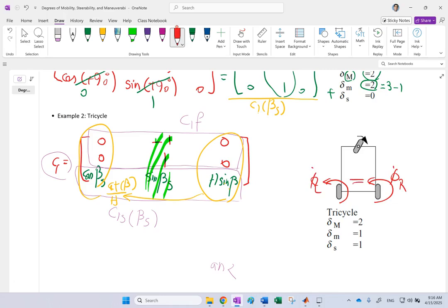In that case, the only motion you can have is forward and backward. So in order to get the turning, you can get your theta dot from the steering motion. So that can give you the whole chassis theta dot. Okay, so you don't really need a differential drive in this case. They can spin together, which makes the mechanism a lot simpler.